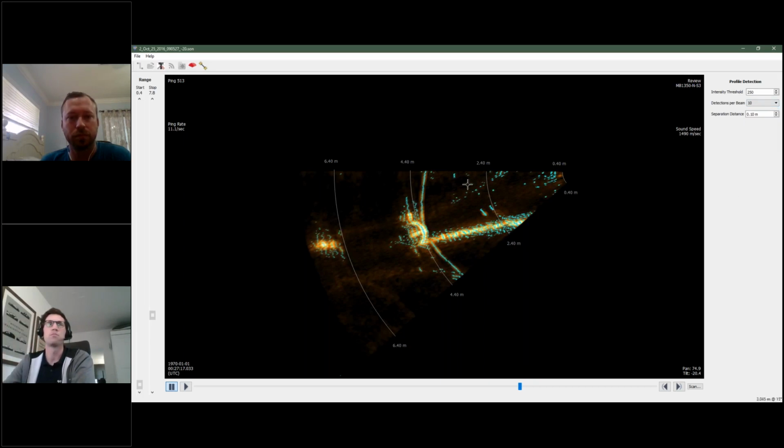So just right there, you can see how many points I'm now getting. In fact, it's a huge excess of points. This is going to be an incredibly noisy, really unappealing point cloud. And I've never really needed to use 10 multi-detects. So that's kind of excessive, but you can see the example if it's picking the 10 strongest points along each individual beam. So 256 beams times 10 points per beam, that's a lot of points.